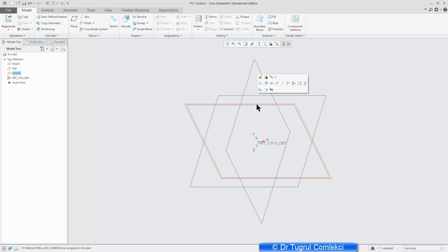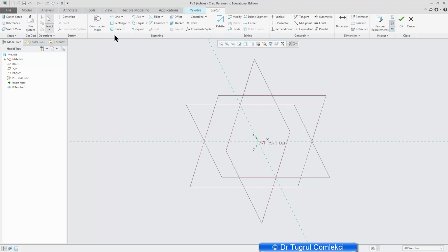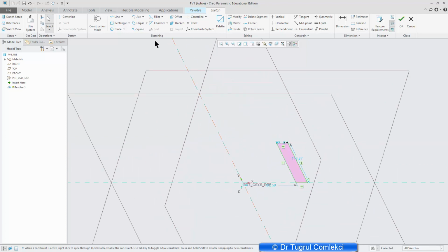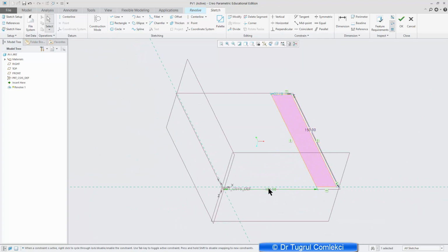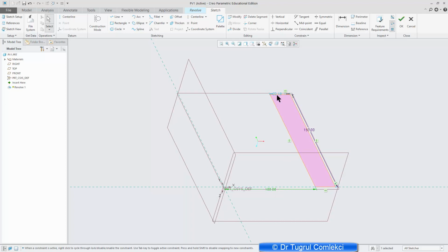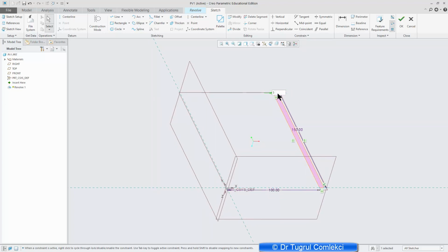So I'll select the XY plane to start a sketch where I'll create a cross section of this vessel that we looked at in the class and define our 2D axisymmetric model. So this is the wall of the vessel in this straight part, which is 150 millimeters long and 100 millimeters inside, and originally has 5 millimeter thickness.